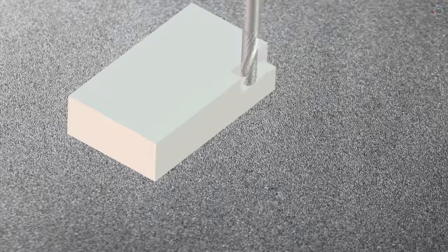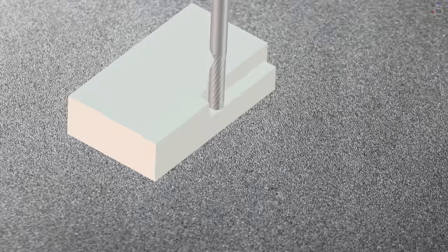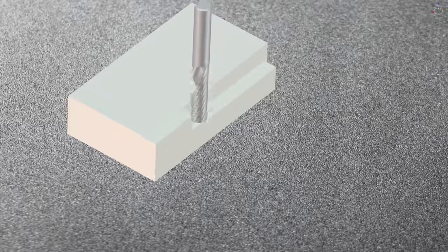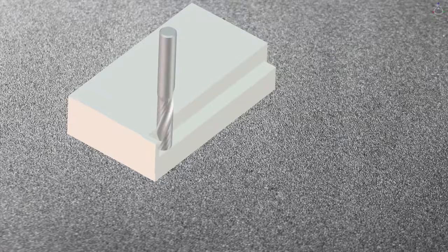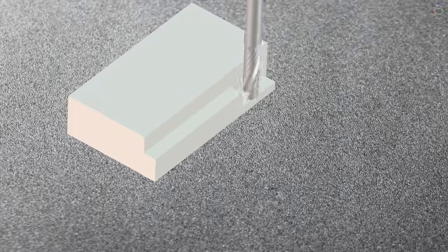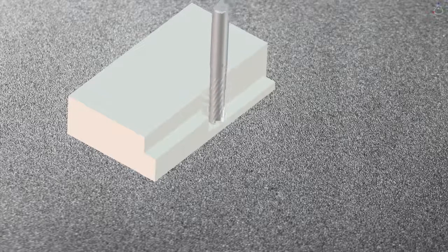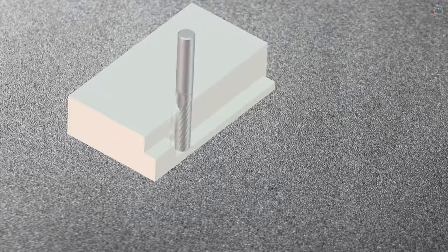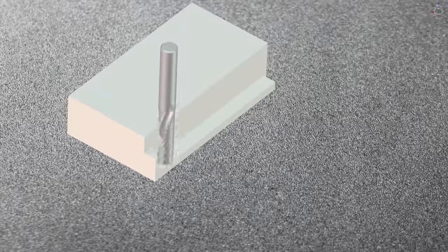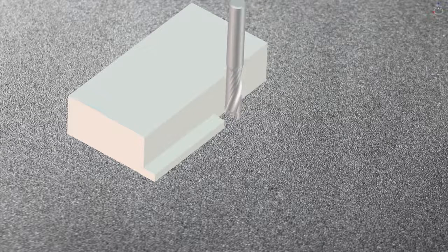In order to be able to process thick panels, multiple passes must be performed. In pass 1 and 2, the in-feed depth for each pass is predetermined by the router diameter and the material. In pass 3, the material is not completely cut through on the penultimate pass. A thin strip with 0.2 to 0.6 mm thickness is left in order to maximize the effect of the vacuum.